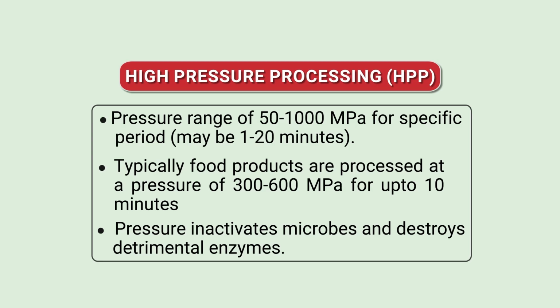You are applying pressure to the product. The product is pre-packed here, and the pressure is exerted on and experienced by the product, and that also causes inactivation of microbes or enzymes. If they are undesirable within the product, they can be inactivated. This technology is suitable for products with high moisture. Water content is high, compressibility of water is good, so they can bear good pressure and can be processed very well using pressure.